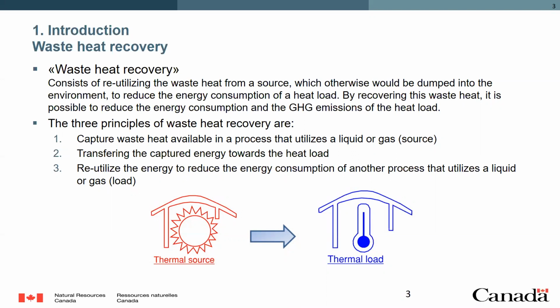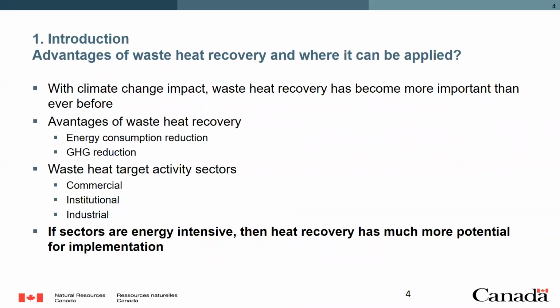Okay, so 2 incentives, one that can turn into an economical one, the other one more of an environmental one right now. What are the 3 principles involved in waste heat recovery? Like I said, first you capture the energy available in one process, whether it is through a liquid or gas, that's a source. You transfer this energy, and you reutilize the energy in the load. So basically you go from the hot side to the cold side, so from the source to the load. As mentioned before, the advantages of doing this are basically reducing your energy consumption and the greenhouse gas emission.